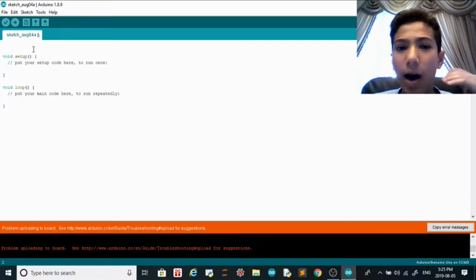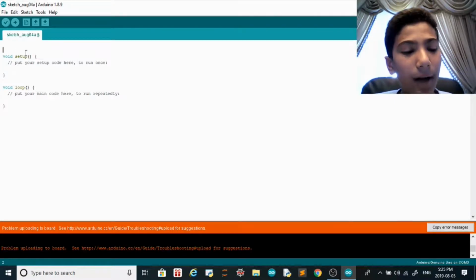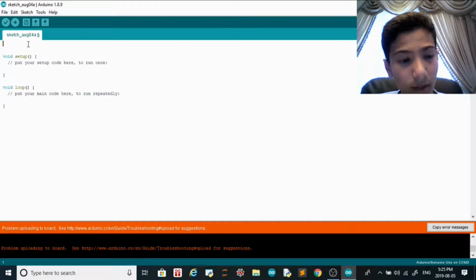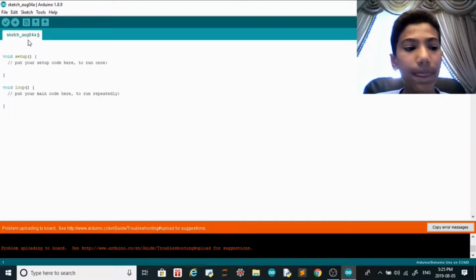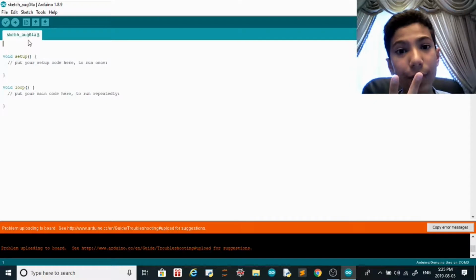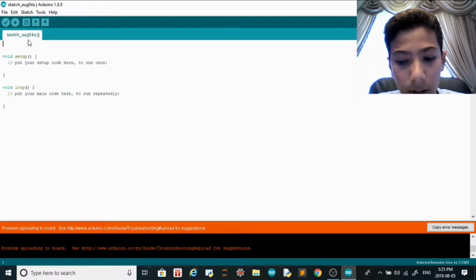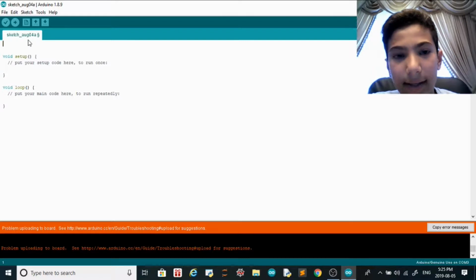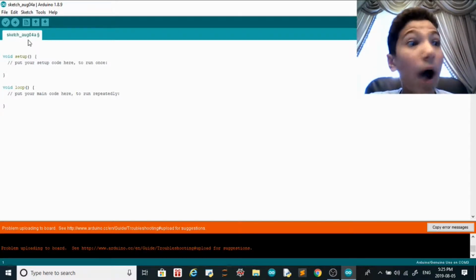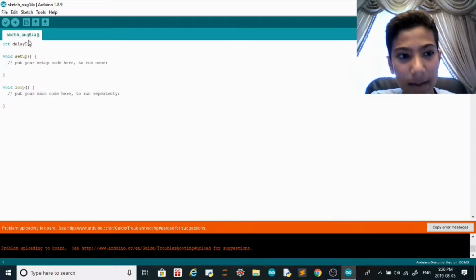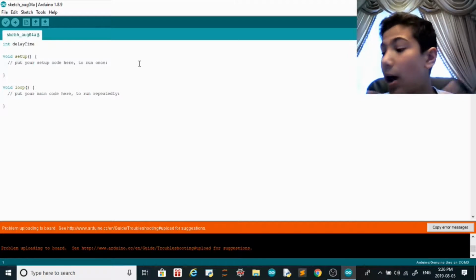Now, how do you create variables? You set them up on top of the setup. Your variable is also made of two words. The first word is what type the variable is. The second word is the name of your variable. Let's say I want to make a variable that is 3. I don't know why it's 3. Oh, actually, I have an idea. Int, it's going to be an integer, delayTime, okay? Because you can actually delay the LED.